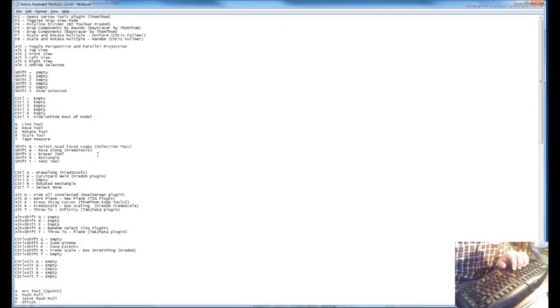So the WER being set to move, rotate, and scale: if you ever use a different software in the industry, 3ds Max, Maya, pretty sure even Cinema 4D, even a lot of the smaller software, early on it was established that move, rotate, and scale would be these W, E, and R, and they seem to be a universal shortcut in the industry, except SketchUp does it differently.